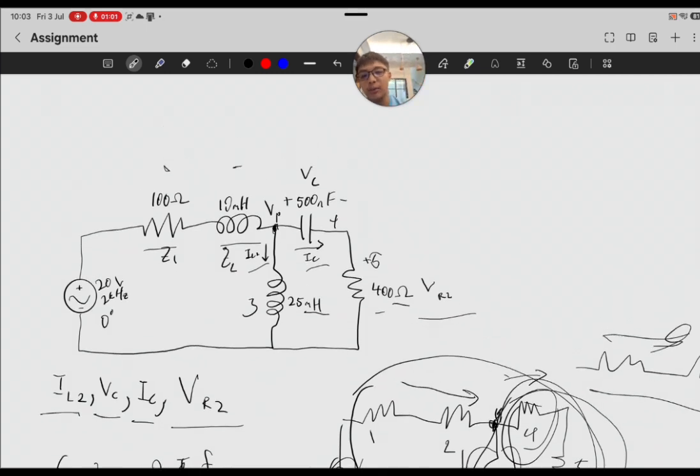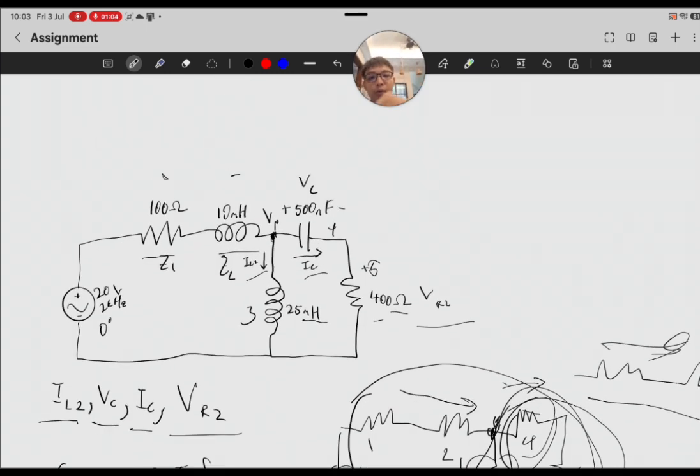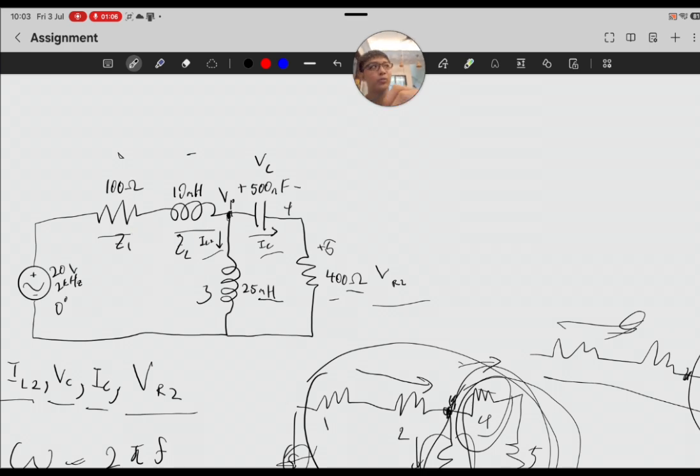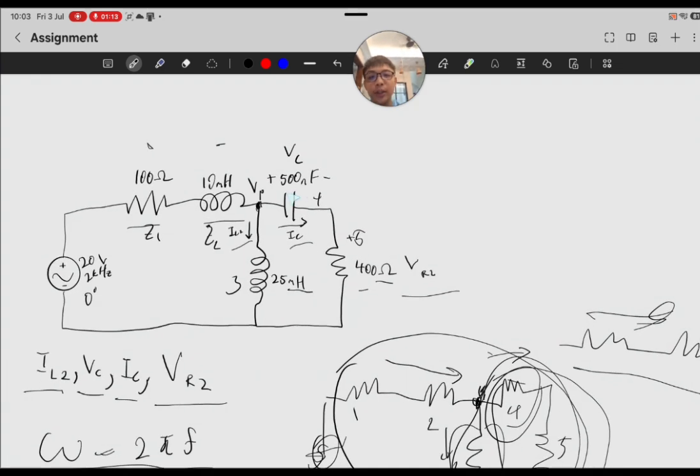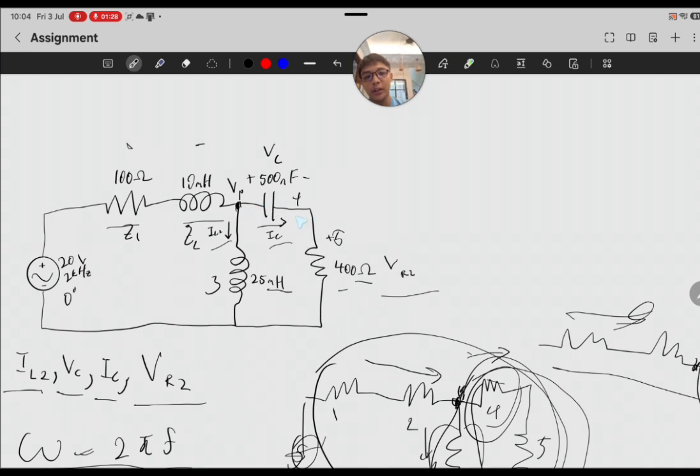So what we do is find the respective impedances and redraw the circuit, assuming that they're all just resistors with complex number resistives. Then what we do next is we first find the total current. Total current is in a polar form where there is actually a phase difference. So first we need to add these two together to get the so-called impedance at that region. So now we only have two resistors in this, not inductors, one big impedance in this region.